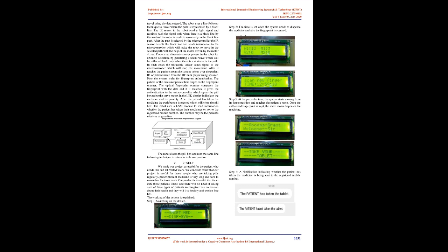already programmed to the prescribed time for dispensing. Our setup includes 3 sessions named morning, afternoon, and night. A 4*4 keypad input is used to set the current time and date. Date and time will be displayed on the 16*2 LCD display. Once the time is set, there is no need to change it again and again because the real-time clock will automatically track the time and date.